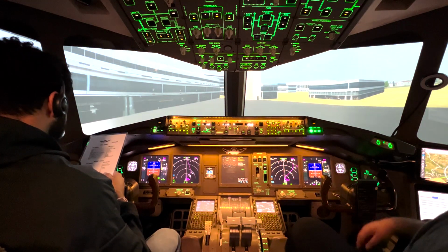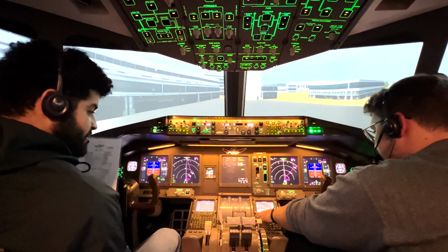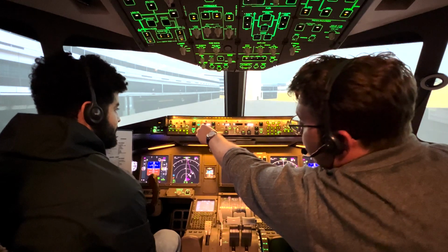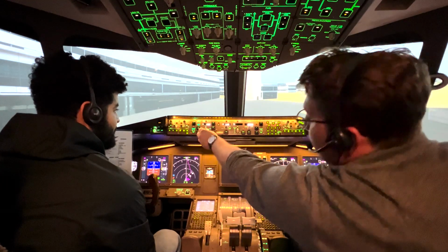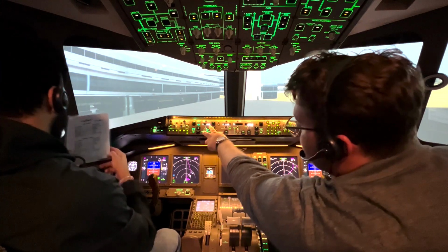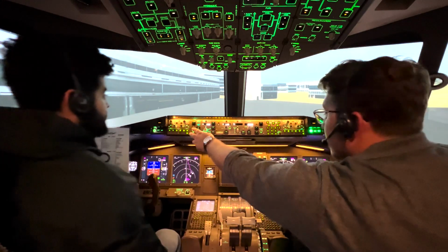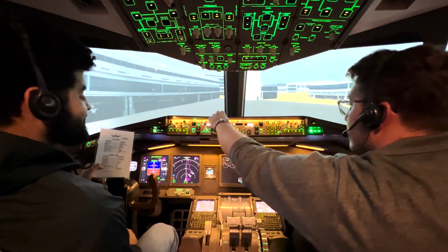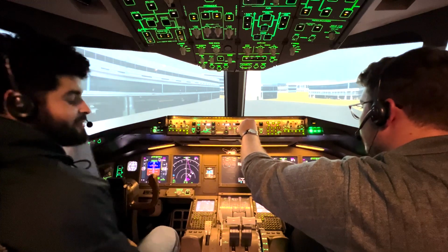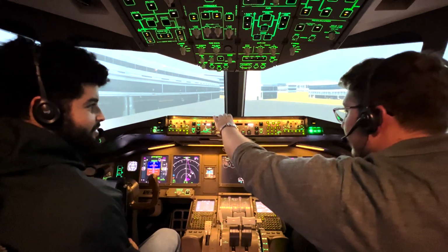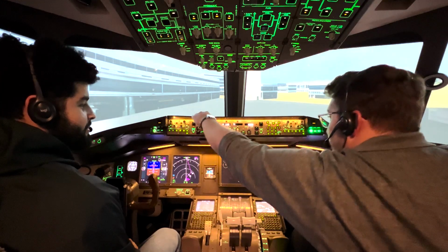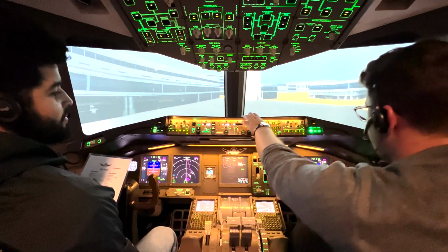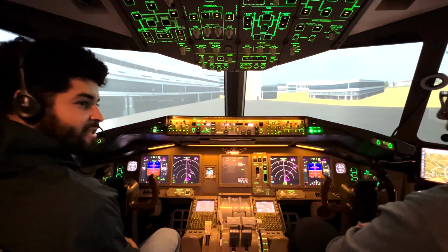MCP. MCP is not set, so that's good that you brought that up. We're going to set our speed to V2, which is 148. Does that say 148 or 146? What does it say there? Here it says 148. Okay. And we'll turn on both our flight directors. We'll arm all the throttles, and set our altitude to 1500, as that's our restriction. We'll do LNAV and VNAV, and that's enabled now. So our plane will be able to fly itself or give us instructions on how to fly after takeoff. So the autopilot, that means it's active.